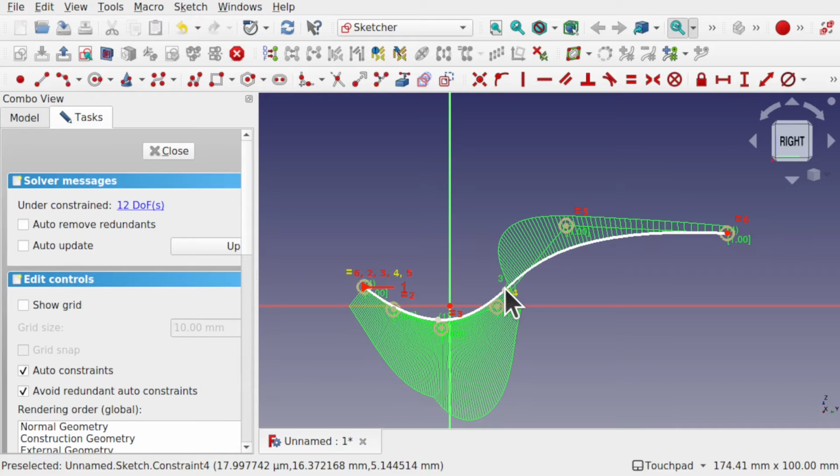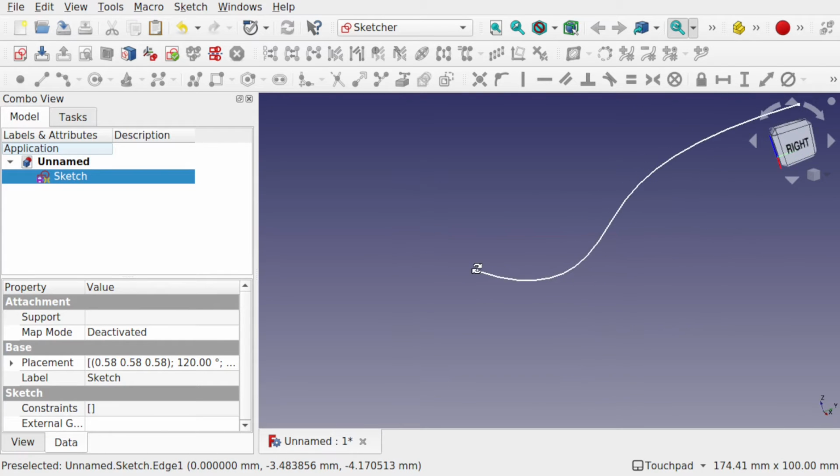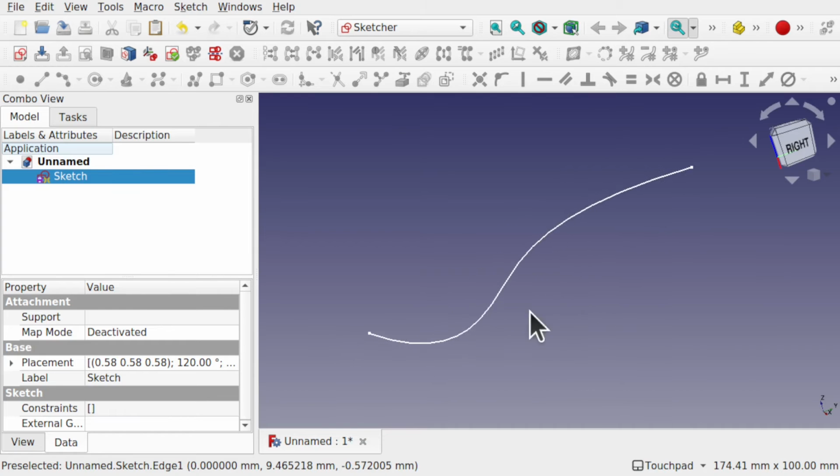And this is where we want to have some kind of reference in here for our top sketch to look down, because the neck of that fork, when it comes round, should line up with the top sketch as well to get our curvature correct. Now the fork is quite easy because it hasn't got any curvature. I hit close, it hasn't got a curvature going this way. So we have our fork, and I'm going to extrude this forwards.